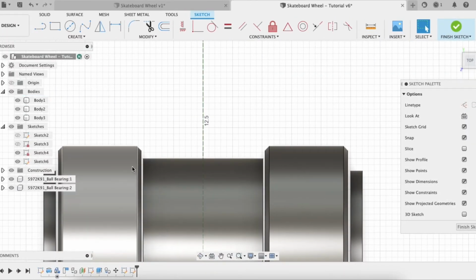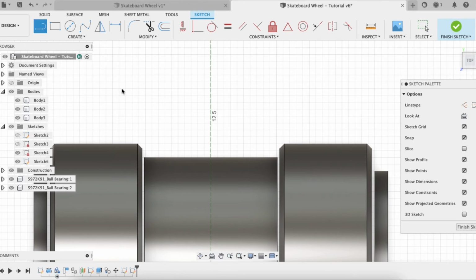So let's get started. We're going to use the line tool, draw a point on our vertical line, doesn't matter where exactly, and let's get started. So we know this guy was 5.75 millimeters, and then we're going to draw a line straight up. Doesn't matter the height because we're going to add our dimensions once I complete this. So I drew a straight up step, and then this is 7 millimeters to the right. So now we have these 3 lines that are to the right of our vertical axis.